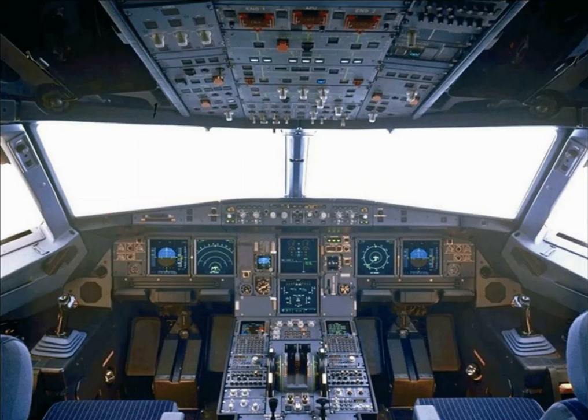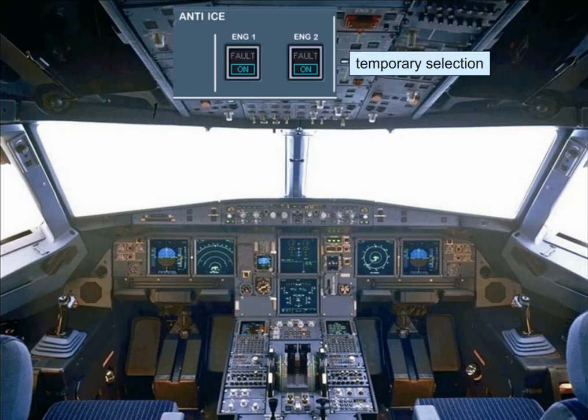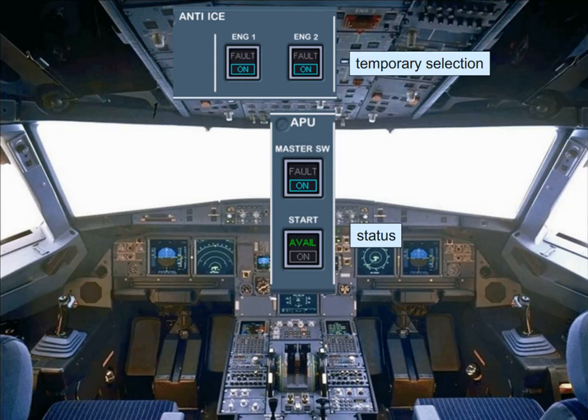On the overhead panel, some push-button switches are used on a temporary basis, or may have an indication of their state. The logic is temporary selection for operational reasons, blue on light, for example, anti-ice. Applicable system status, green light, for example, APU available. You will see this philosophy demonstrated throughout the course.